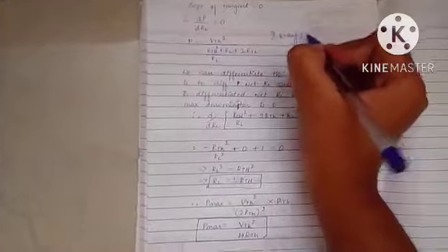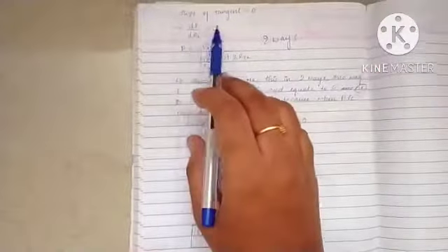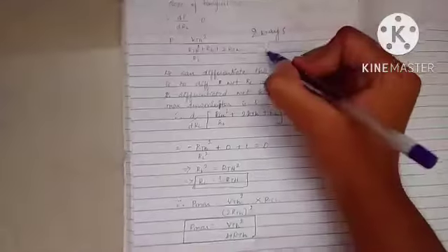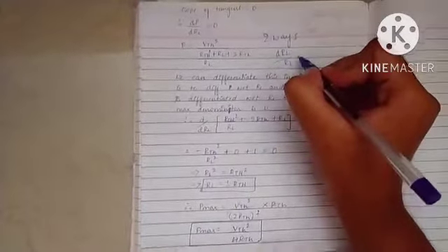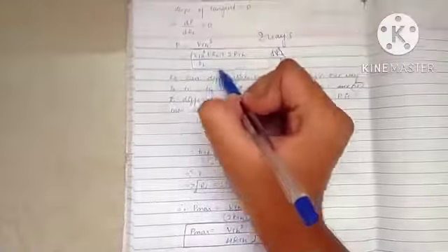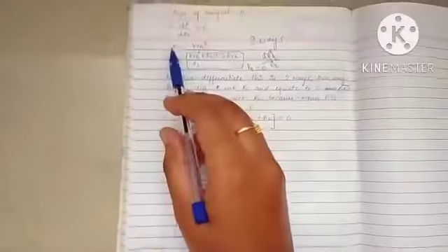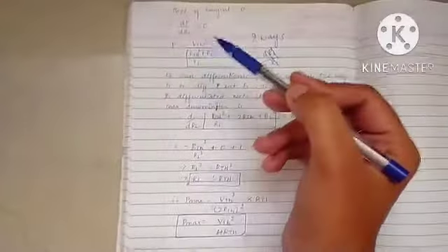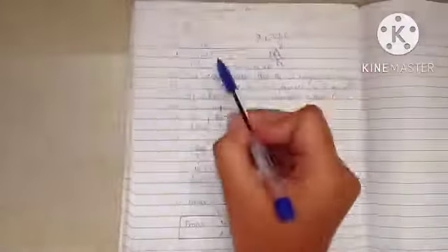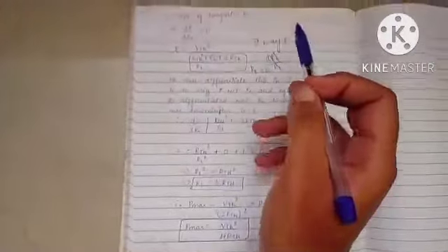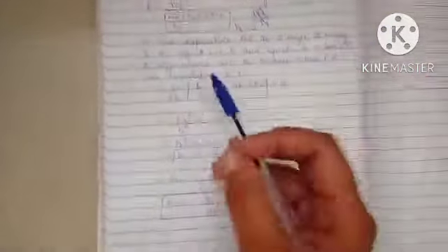Here, there's an understanding. We can differentiate it in two ways. One way is dP by dRL equals 0, and the other way is to differentiate this denominator with respect to RL and equate it to 0. Okay, so we have two ways. Why differentiating this denominator with respect to RL and equating to 0 works is that when the power is maximum, this term is very minimal, right? So when this term is minimal, we can equate it to 0. That is why we can differentiate this directly and equate it to 0 with respect to RL.